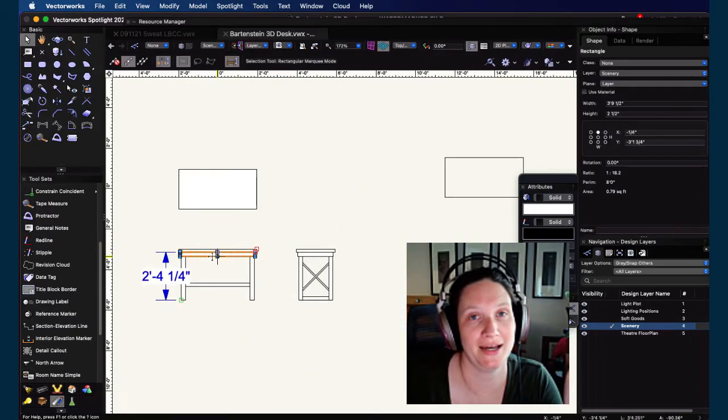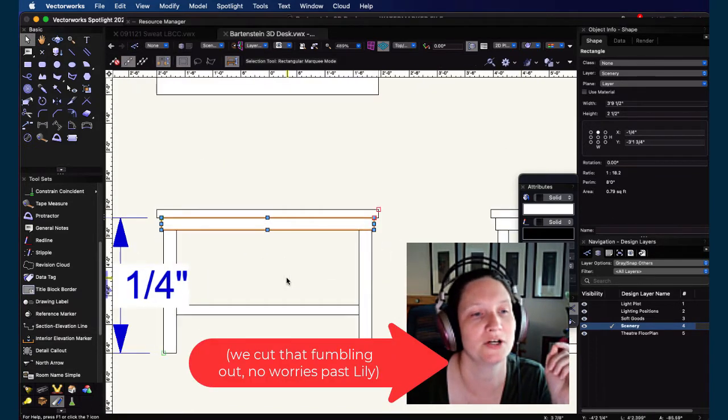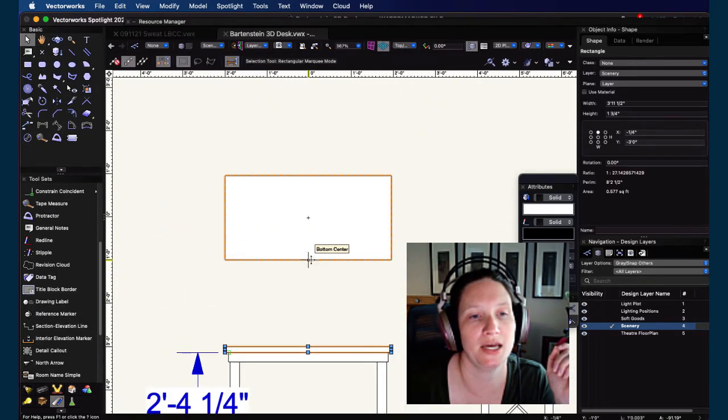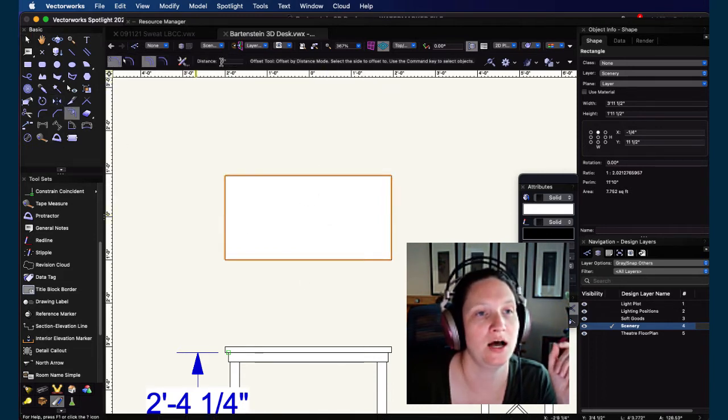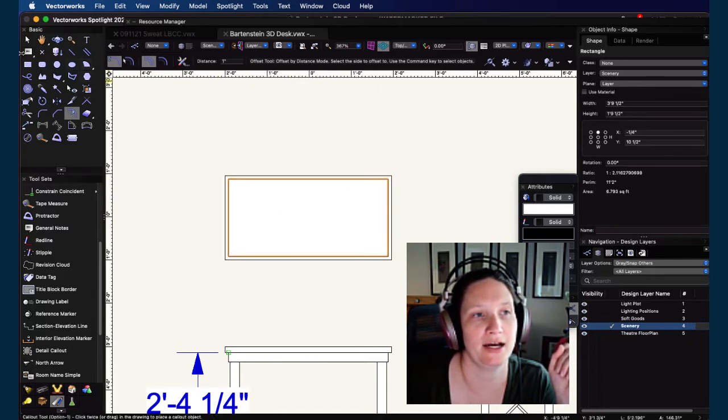So now I want to create this rectangle that sits underneath. So let's take this rectangle underneath, okay? So we know if you look up here, it is a whole inch on each side less on each edge, right? So in order to make a copy of it, I'm actually going to come back to my lid rectangle, pick up my offset tool, take that 1 inch offset distance, click inside, and now I have this rectangle.